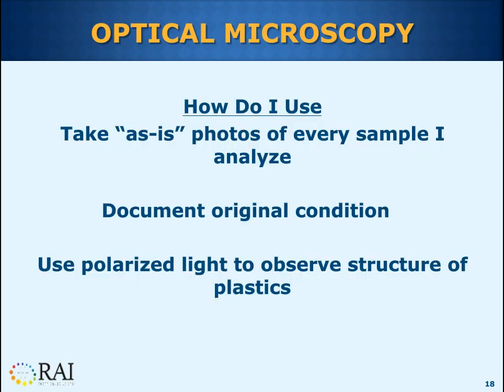Optical microscopes are general-purpose instruments. I use them to document the original condition of almost every sample I analyze. The polarized light feature is very helpful in my work in determining the structure of plastics and why a plastic may have failed in service.